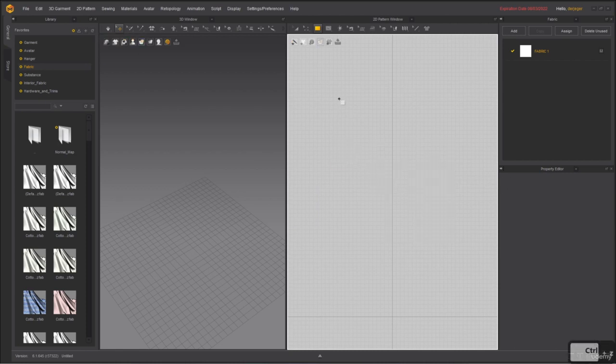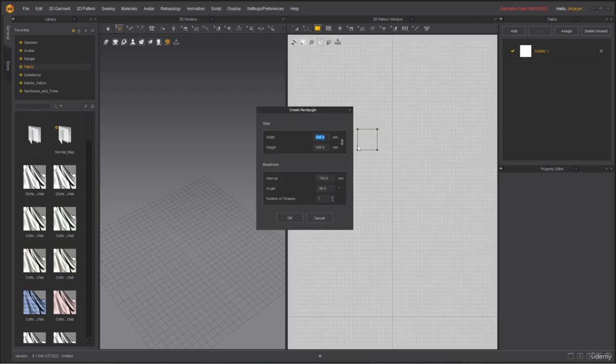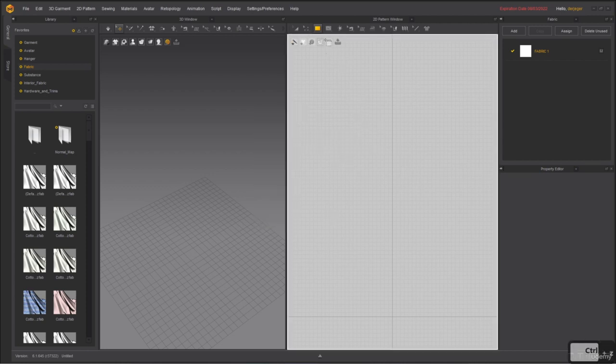Right click to create 2 different types of polygons. Sorry, normal click. It's just a normal click. Hit cancel. The other one is the ellipse, and it's very similar. You can press and drag to create an ellipse. If you press Shift, it's going to be a perfect circle.